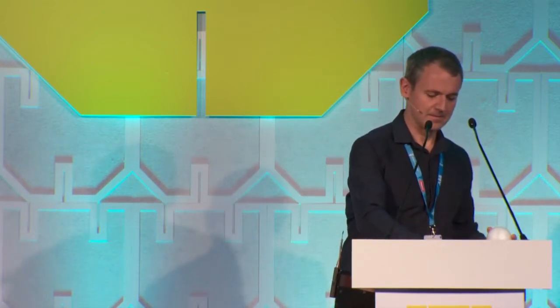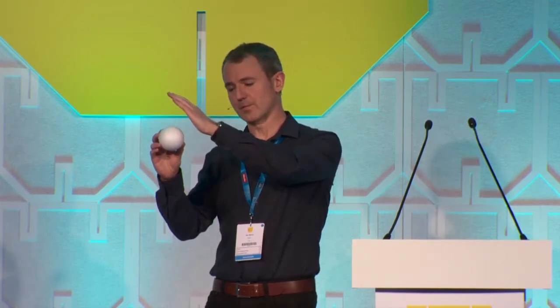And it's actually demonstrating exactly how aircraft fly and how wings work. And that's that the weight of gravity is pulling down on the ball, which is pulling it out of the airflow slightly. I'll just turn that off. And as the ball's dropping out of the airflow, what we're finding is that you end up with the higher speed flow over the top of the ball and atmospheric flow underneath it. And higher speed flow has a lower pressure. So there's a pressure difference between the top and the bottom of the ball, and effectively the ball is being sucked up by that vacuum.